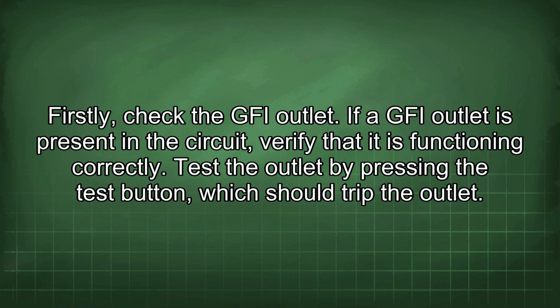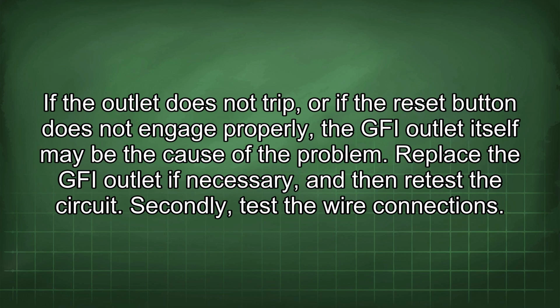Firstly, check the GFI outlet. If a GFI outlet is present in the circuit, verify that it is functioning correctly. Test the outlet by pressing the test button, which should trip the outlet. If the outlet does not trip, or if the reset button does not engage properly, the GFI outlet itself may be the cause of the problem. Replace the GFI outlet if necessary, and then retest the circuit.